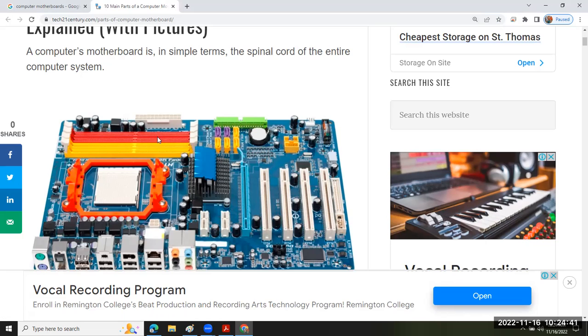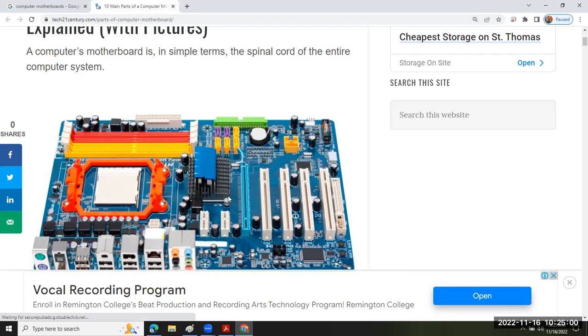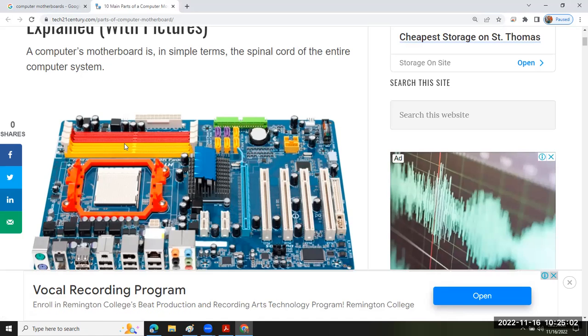In most motherboards, it's best to put DIMMs in sets. So you'd want to put them in pairs, and in some cases in threes. There were some Mac Pros, and some other high performance designs that actually had them in threes.